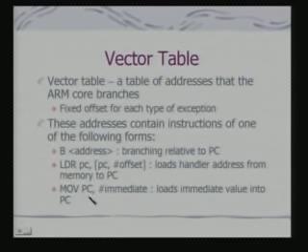In this case, move PC immediate, this is also an immediate address which can be loaded onto the PC. This gives you the ability to locate the interrupt handler anywhere in the memory, because the immediate operand can be appropriately changed and loaded onto the PC to provide the address. In this case, it is always a relative address.